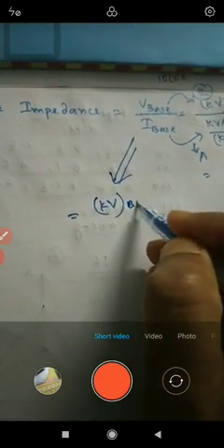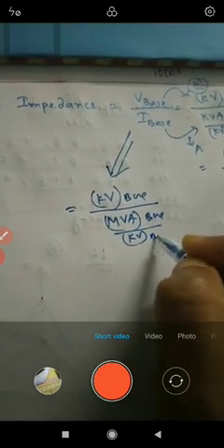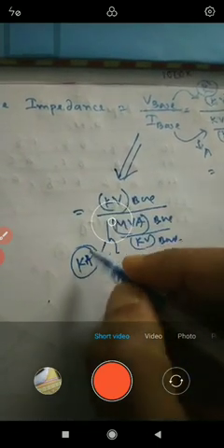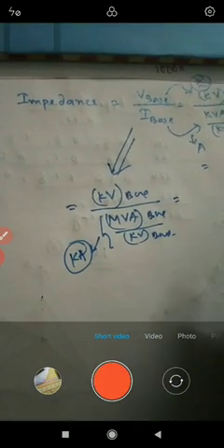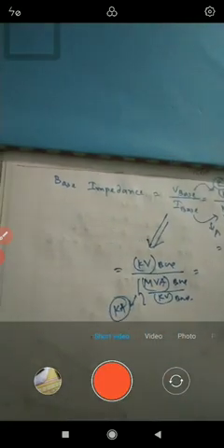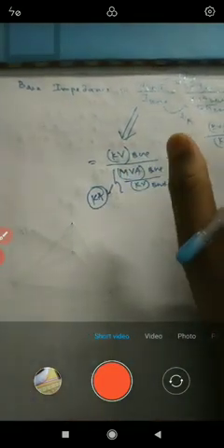There is another formula for I base. If I use that one, kV base by, that is I base, what? In MVA I have given MVA base by kV base. So what happens here? The I base itself is in kilo ampere. So it is kilovolt kilo ampere, so no need of 1000. So you can go by this one also. There is no confusion of 1000s. So I prefer you remember either way, just take care of units. You give mega means 10 to the power 6, kilo means 10 to the power 3, and everything will automatically cancel out. Both of these are given in your notes.